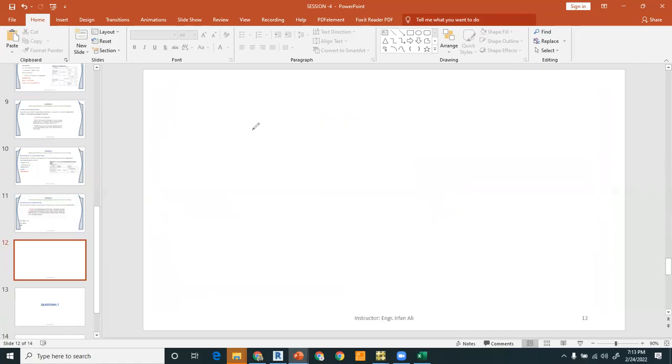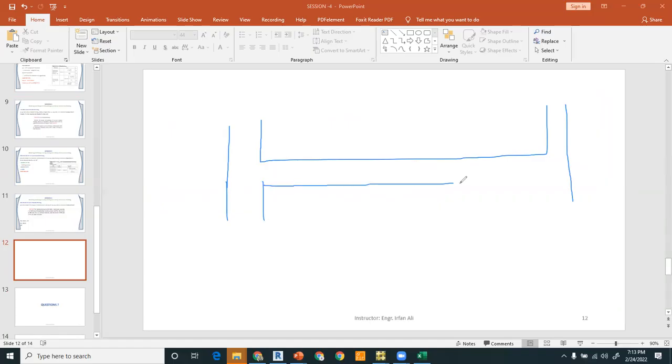So if I draw a beam, for example, this is the typical beam which we provide to the client. So these are the longitudinal reinforcement, top reinforcement. So this is, for example, longitudinal bars. These are coming. So it will show you a cut in here, and some of the bars will go continuous. Right. So there will be a cut, and this is the bottom reinforcement.